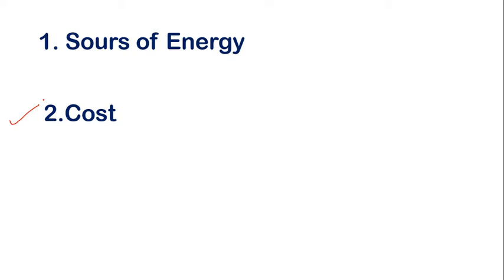Annual cost is considered in two types. The first type is the annual fixed cost, and the second one is the annual running cost. The fund required for the land, building, plant and machinery, etc., is borrowed as a loan, and annual interest has to be paid on this borrowed capital. In addition, some amount has to be kept aside every year as a depreciation charge on the cost of the plant and machinery. So the annual fixed cost includes the cost of interest and depreciation on the capital amount.